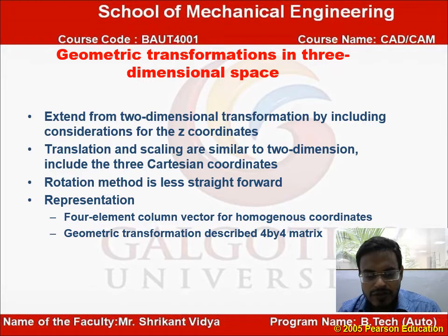A three-dimensional object has a three-dimensional geometry, so therefore it requires a three-dimensional coordinate transformation. A right-handed coordinate system is used to carry out a 3D transformation. The scaling and translation transformations are essentially the same as 2D transformation. However, the points matrix will have a non-zero third column. Additionally, the transformation matrix contains some non-zero value at third row and third column.